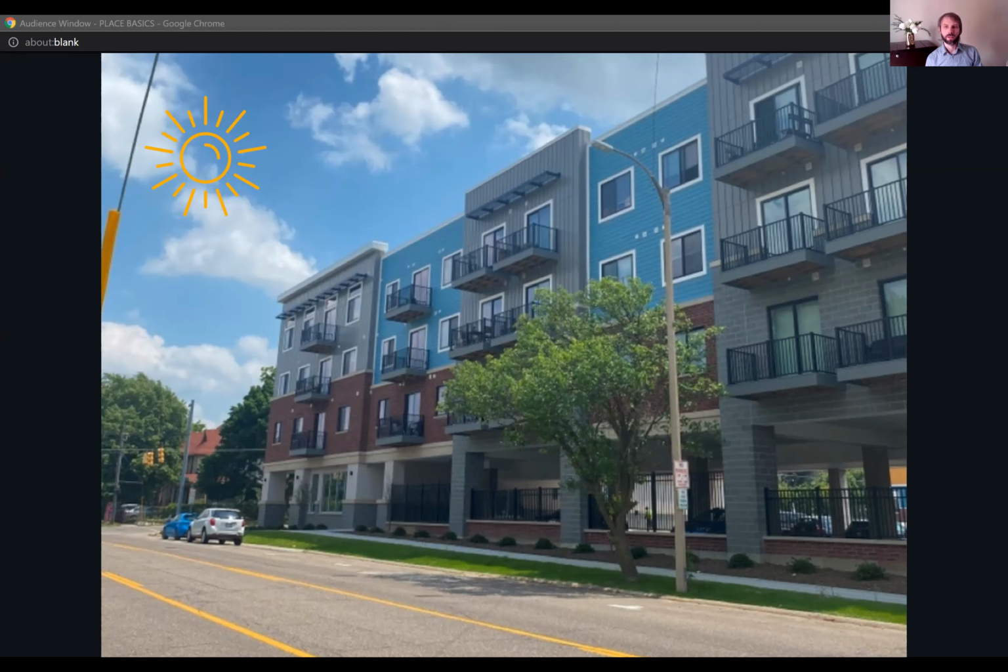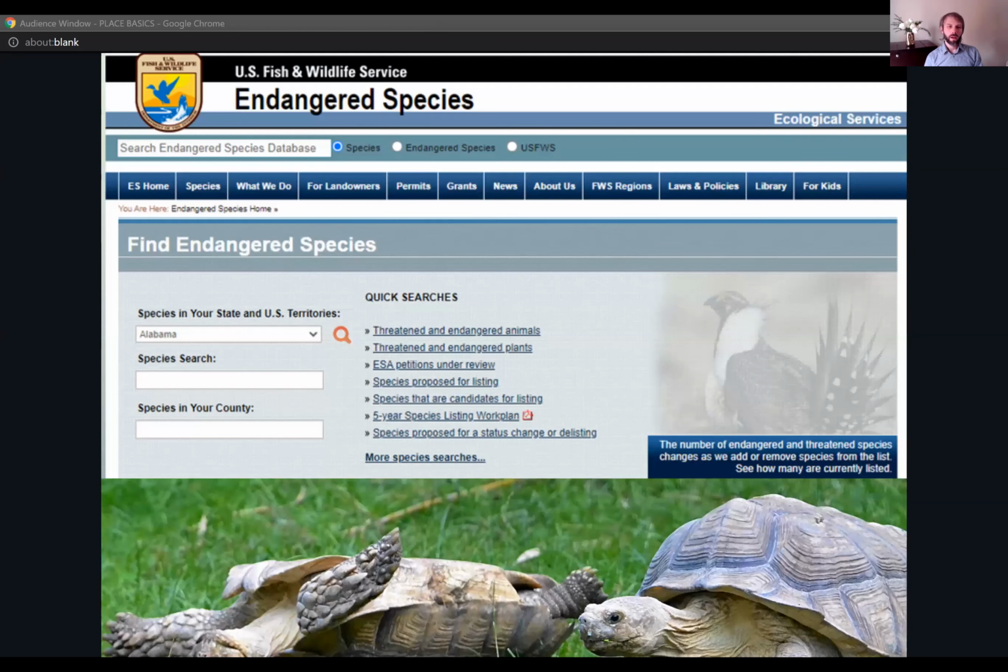need for transportation. And also, multifamily buildings inherently are always going to use less energy than single family just by the way they're built. So if you had a 2,000 square foot single family home and a 2,000 square foot multifamily unit, that 2,000 square foot multifamily unit in the same climate is going to use a lot less energy, even if it has less energy efficiency features. And so it's much more efficient and much easier to go electric and use heat pump applications because it has less heating demand, especially in cold weather climates.